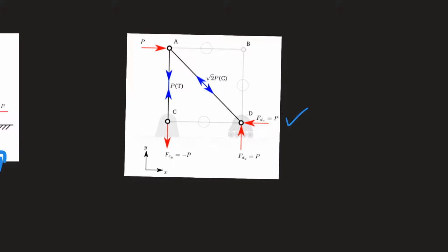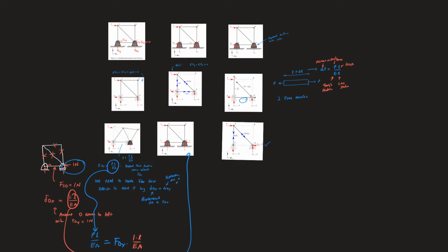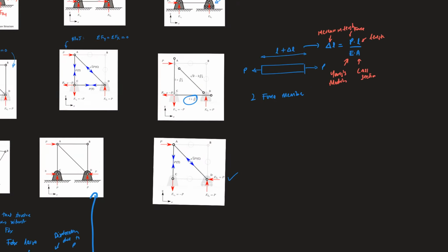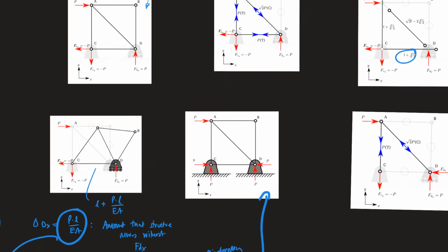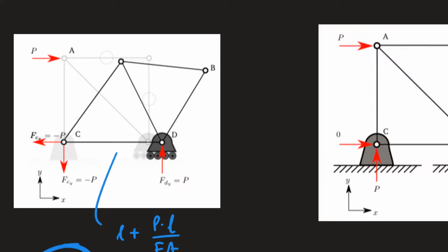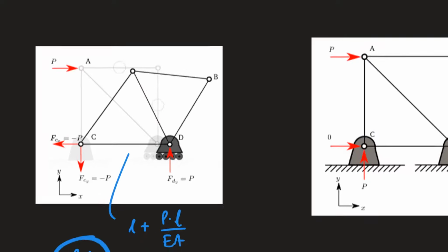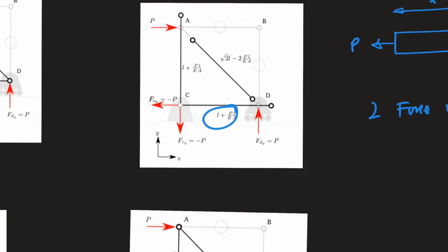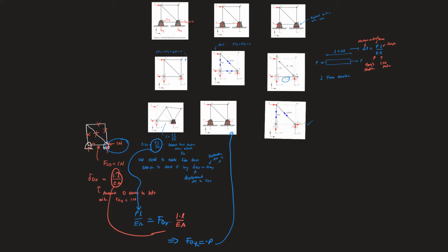We've solved for a statically indeterminate structure when we've got a redundant external support. So the method is valid, and it's the method we're going to use. Where it becomes difficult is this one was a little bit easy because we could see that the movement of node D is equal to the extension of this bottom member. If we'd had to actually go through and unpin them all completely and work out the displacement due to geometry, then it would be a whole lot more complicated.